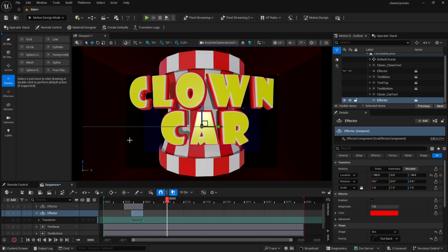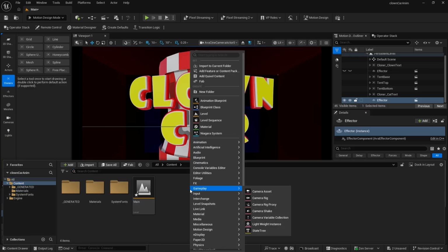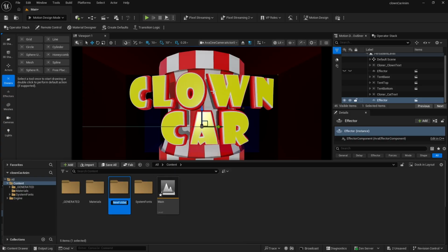Now I'm going to animate our little car. I showed you earlier the link to that. If you downloaded that, unzip that file. I'm going to bring it in as a GLTF. Over here to the content drawer, I'm going to go back to contents and I'm going to set up a folder for this. I'll go up here, new folder, and I'm just going to label this Clown Car.